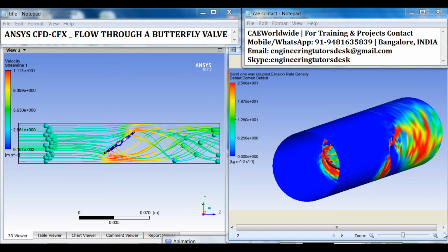The K-epsilon turbulence model is the most common model used in computational fluid dynamics to simulate mean flow characteristics for turbulent flow conditions. It is a two-equation model, which gives a general description of turbulence by means of two transport equations. The original impetus for the K-epsilon model was to improve the mixing length model, as well as to find an alternative to algebraically prescribing turbulent length scales in moderate to high complexity flows.